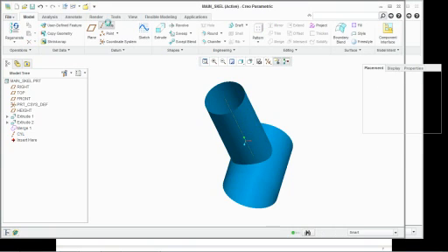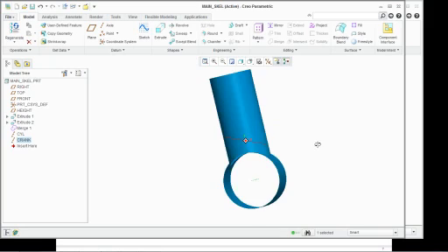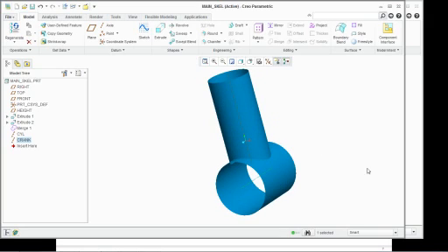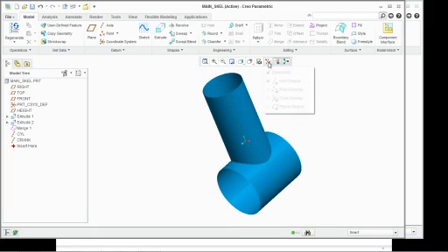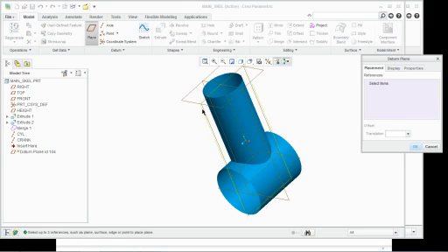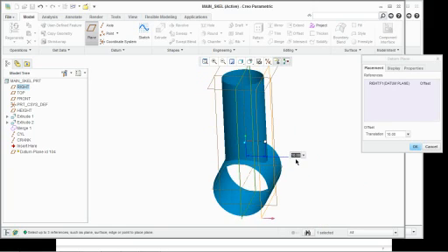Then we're going to insert another one in the bottom down here. We're going to change the name of this to crank. And then we're going to come in and create from the top plane here. We're going to select our top plane. Or I guess, actually, I'm sorry, I need to turn my planes on. So you can see I'm going to offset some planes first. First I'm going to offset a plane off of here. We want that to be offset 10. And make that 20. Make it spaced out just a little more.